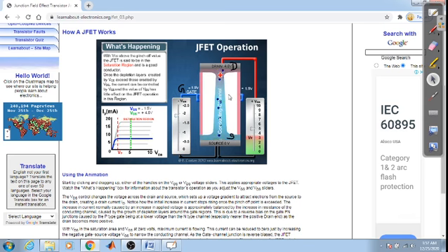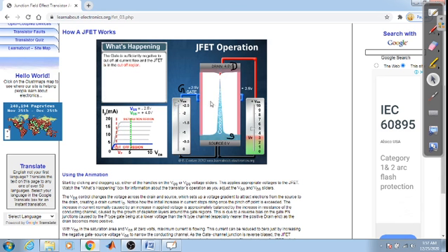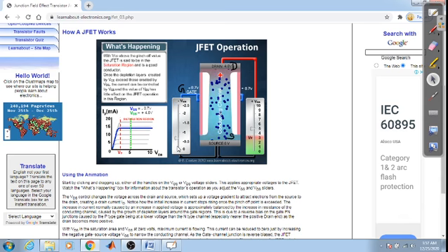So just look over here, the current is decreasing. A higher current was at this 0 location, and it keeps decreasing as you increase the VGS. When it reaches minus 2.5, it is completely stopped, so your JFET is off. So what it indicates is, whenever the VGS is at 0 volt, the channel will be open and the JFET would be in on state.